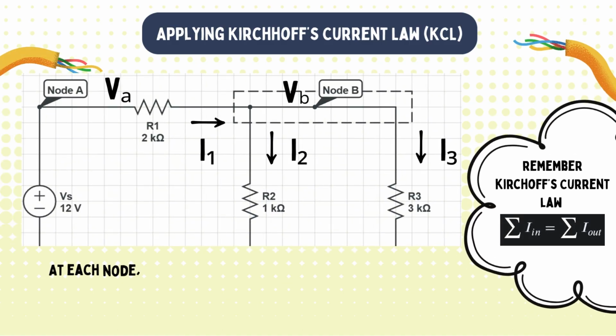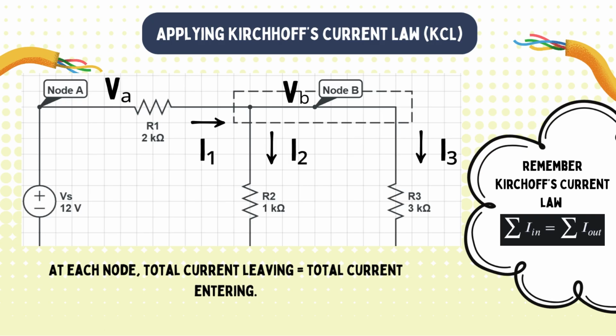Applying Kirchhoff's current law. Now we apply Kirchhoff's current law to each node. At every node, the sum of currents leaving the node equals the sum entering it. We will write one equation for node A and one equation for node B based on the currents through the connected resistors. This is the foundation of nodal analysis.